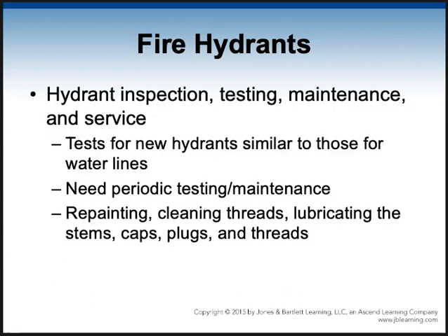Okay, we're almost done. When fire hydrants are put in, they have to be inspected, tested, and maintained. So when a new hydrant goes in, we test it to make sure it's got the right pressure and that it is made correctly. But then every year we go out and we test them all. We open every single fire hydrant in our district, and we might even do a little maintenance, like repaint them or clean the threads. If anything is broken, we'll report it to the water company. If caps or plugs need to be replaced, we'll do that. If threads are really bad, we might report that to the water company and they'll replace the whole fire hydrant.